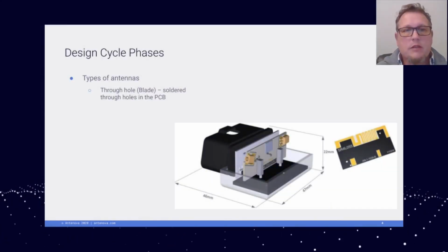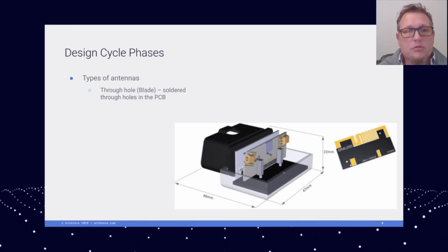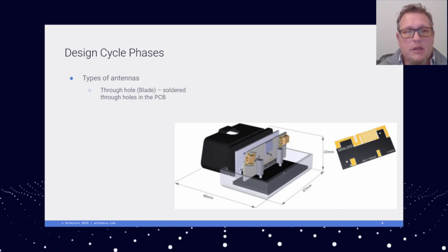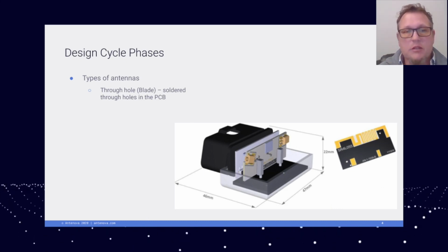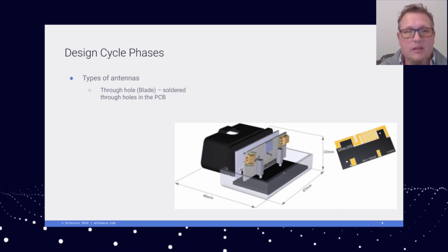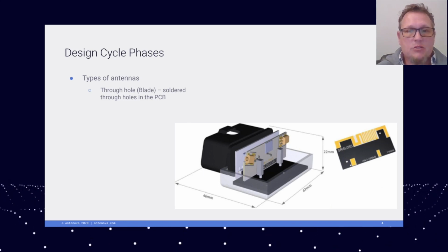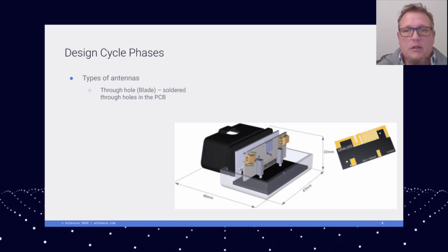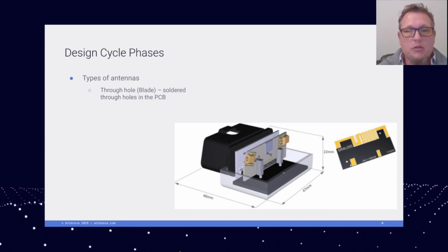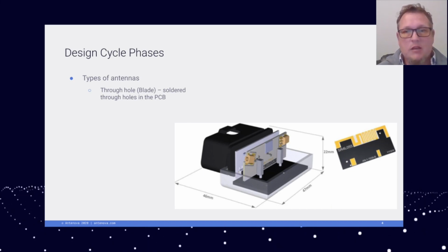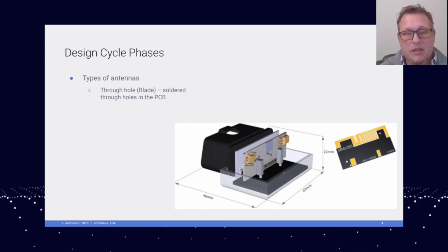The next antenna type I'd like to go over is the blade antenna. Blade antenna is used to shorten the overall device length when your device needs to be small, such as like the OBD or onboard diagnostic devices. These blade style antennas require the interaction of a pogo pin or something to contact between your main PCB and some pad landing points on the blade style antenna.